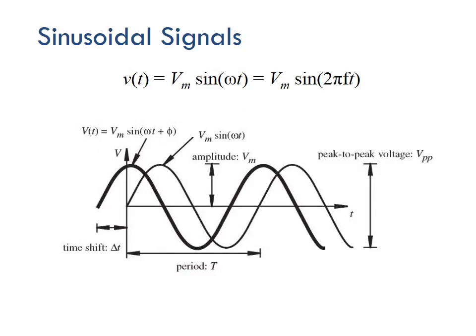This slide is a refresher in case you forget your physics 2 from E&M and wave theory. Here's a sinusoidal signal and the equation for sinusoidal signals. We're going to look at them in terms of voltage over time in this class, because that's usually the most important. Like an alternating current signal, the voltage is going to change as a function of time. That's generally what we're looking at in electrical. So V of t equals Vm sine omega t, or if you want to break omega down, you can get Vm sine 2 pi ft, where f is the frequency.